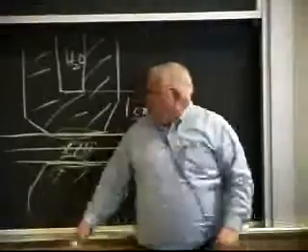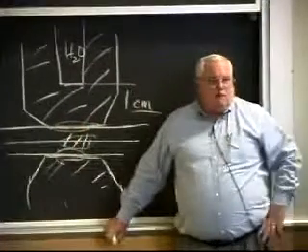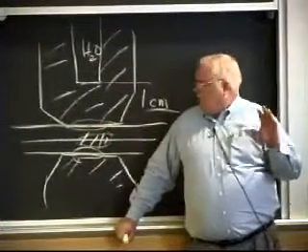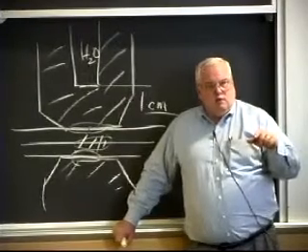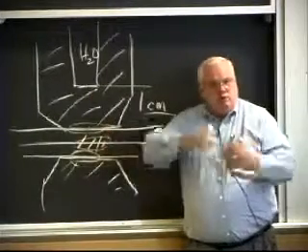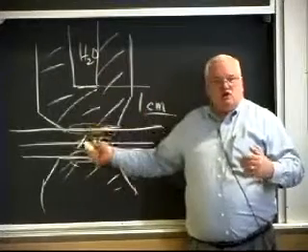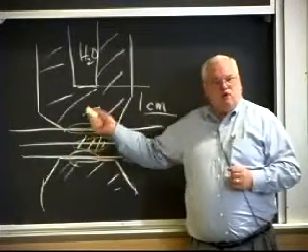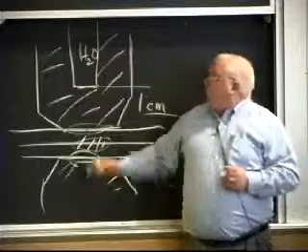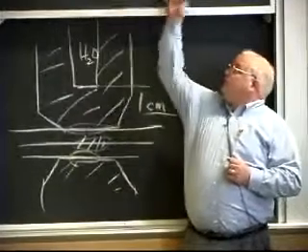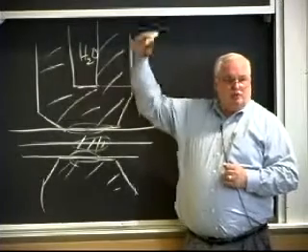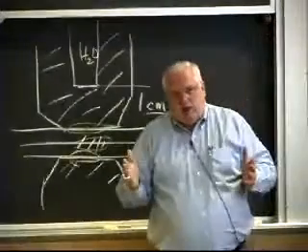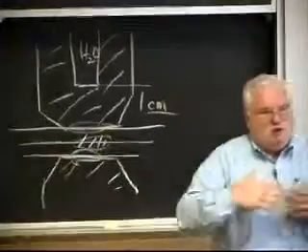In the automotive industry, they make 20 spot welds per minute. So I've got 3 seconds between each one. After I separate these things, will that water cooling actually help cool the surface here before it goes and makes the next weld? Well, if you look at this, I'm kind of somewhere between this and this. So I will get some cooling, but I won't get too much cooling. And in fact, we've run experiments. It shows that it takes 15 or 20 seconds to get to some sort of thermal equilibrium when you start doing that rapid spot welding.